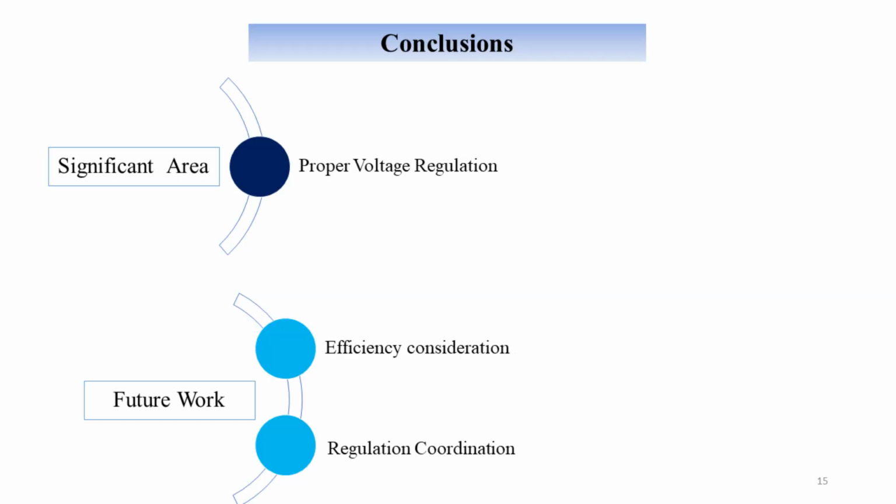In conclusion, we have presented an optimized Class E driver design for inductive WPT. By refining the selection of the current limiting choke inductor, our circuit reliably provides a stable, regulated voltage higher than the source to a remote unit. This addresses a key challenge in WPT systems. Future work will focus on further improving overall system efficiency and developing coordination methods for voltage regulation under varying coupling conditions.